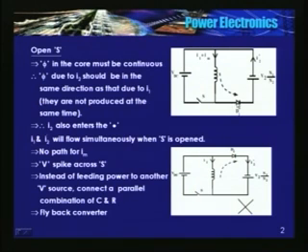What happens if I were to make a small mistake in the diode connections? In other words, both the windings were to carry current simultaneously. This is the equivalent circuit. Close the switch, current flows in this direction. So, current can also flow in the secondary. Okay. Magnetizing current was in this direction, remember.